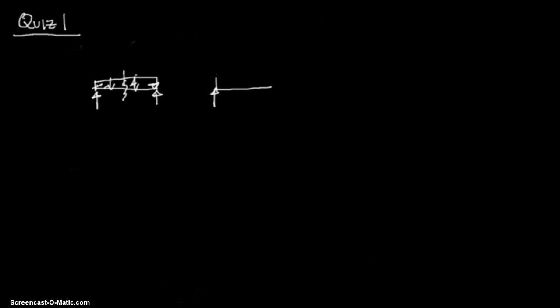And every time you cut, as I had said on an example in the past, we cut it at this point right here. You have to have a vertical, which I always call V, then the horizontal, which in this case is an axial load or a tension or a compression, so I usually call that P, and then I have a moment.